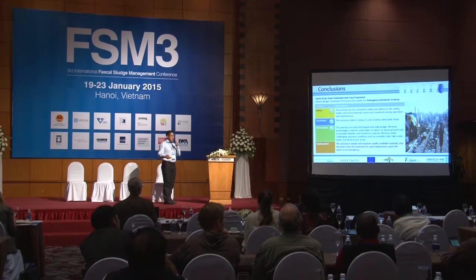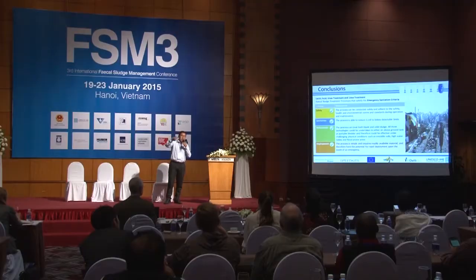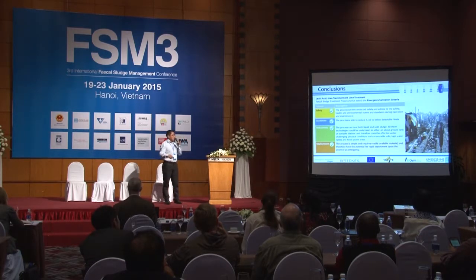These treatment methods are robust because we dealt with different kinds of fecal sludge, and we got good results in all of them. And it's easy to deploy. For example, thinking of lactic acid, the idea was you just take your small bottle of Yakult and travel to the place, mix it with milk, and you prepare your inoculum, and you can start treating. And also the lime and urea most of the time are available locally.